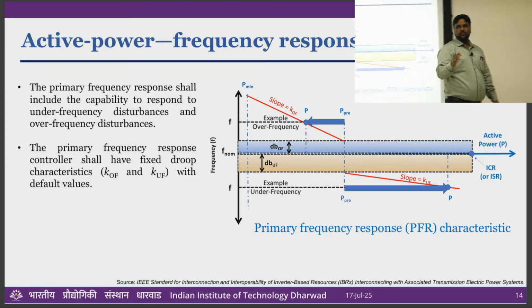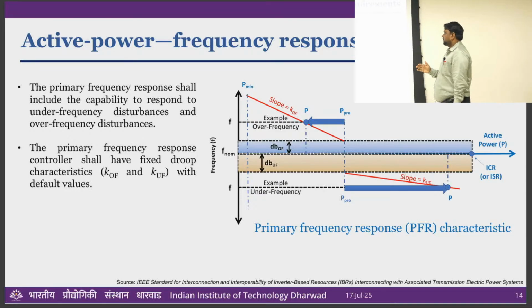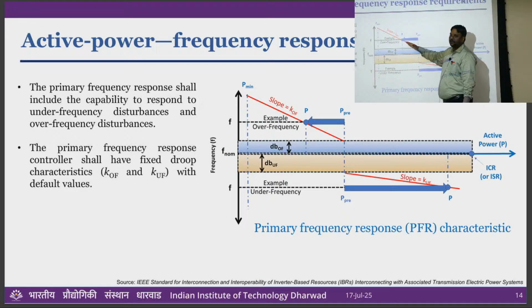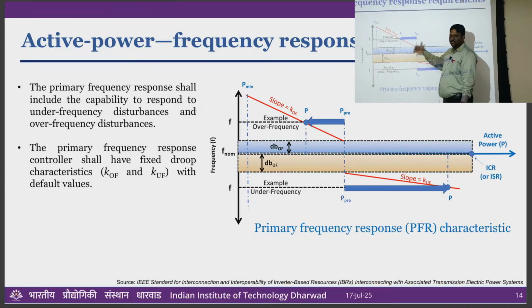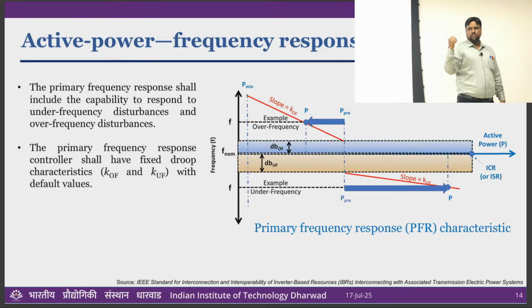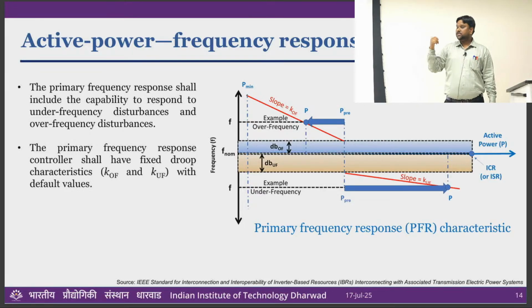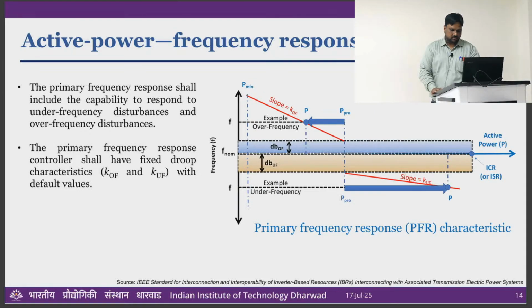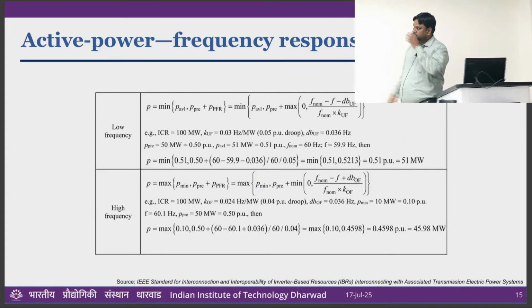It is less turbulent, or slow, you can say. But I will show the next curve, something called fast frequency. Same curve, same relation, but the slope will be different, because slope decides how fast you inject. So primary frequency 2 to 5, they have given flexibility, grid people, you can maintain anything in between that. This is an example again of how to decide.